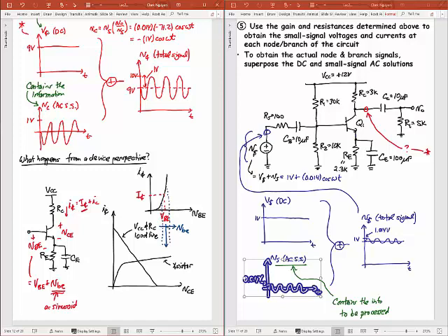And so that's where I'm wiggling my VBE right there. And this is time. That's VBE versus time on that axis, right? So if I wiggle VBE like that, and this really should be a straight line, so I'm trying to make that a straight line. What's going to happen is I'm going to intersect this curve, and that's going to tell me what IC is doing there. But okay, that's not actually what I'm doing here.